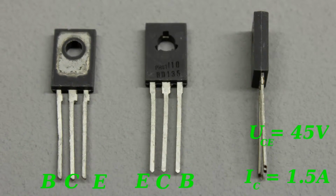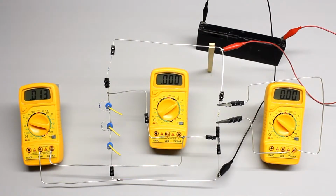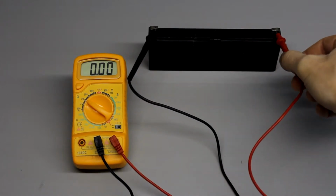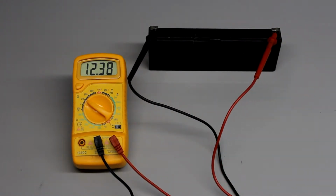of 1.5 ampere. Both values belong to the emitter collector line of the transistor. The first test circuit consists of 3 digital multimeters, 3 potentiometers and 2 constant resistors, plus, of course, the transistor. A lead-acid battery with a nominal voltage of 12 volts is used as a voltage source. The detected voltage of 12.38 volts is considered to be constant during the whole series of measurements.